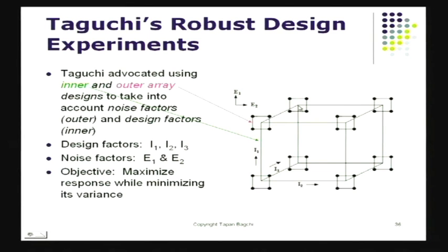So I've got a product, a prototype, and I'm going to be shaking it with the environmental factors. If I've got a product in my hand, I'd try to impact it using environmental factors, which in this case could be a physical force, temperature, dropping it, and so forth. Even the quality of the components could be considered noise factors.